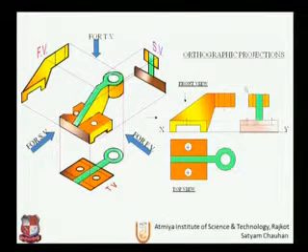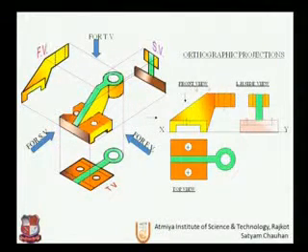Again it will be a center line overlapping this rib section, and to show the center line, to show the holes are drilled here, and by giving the names front view, top view and left hand side view, we are completing the multiple views.